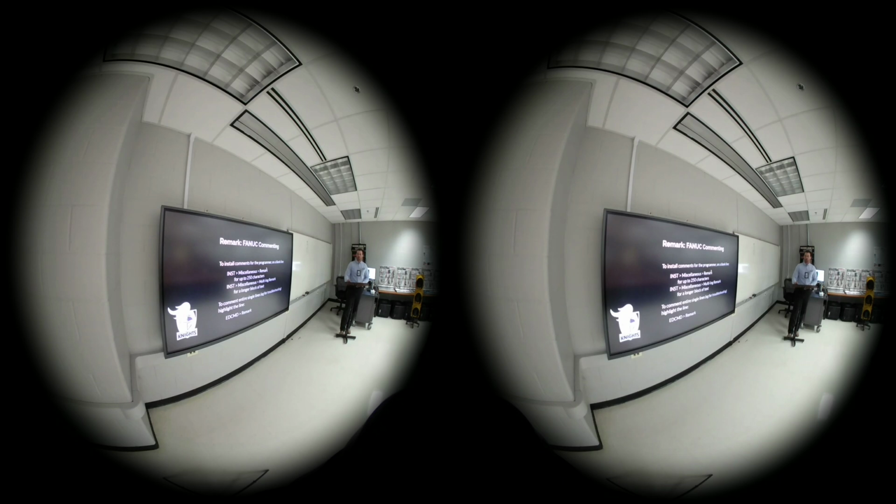So to do a remark for the programmer in human readable language, do the inst key, which is one of the soft keys, miscellaneous remark, and this is wrong, it's not 250 characters, it's way less, something like, well, it depends, but I've seen it as little as 4 characters. But you can also do what they call a multi-language remark, and this will do a huge block of text, and you can write stories or jokes or whatever in there.